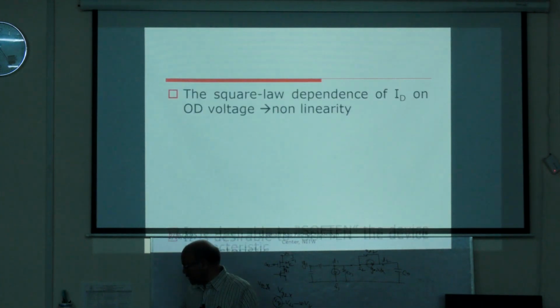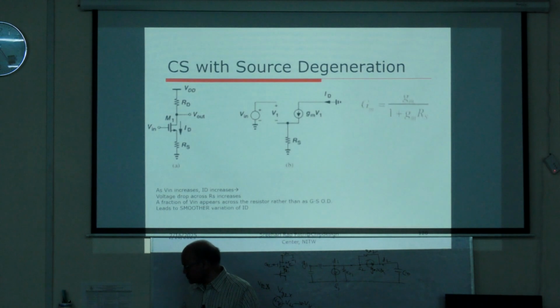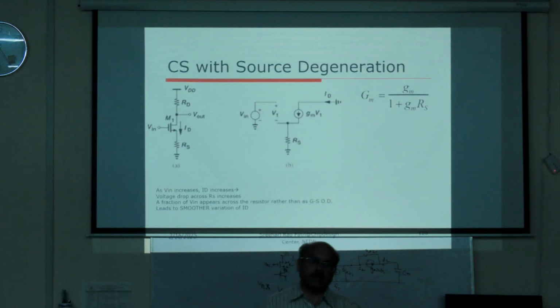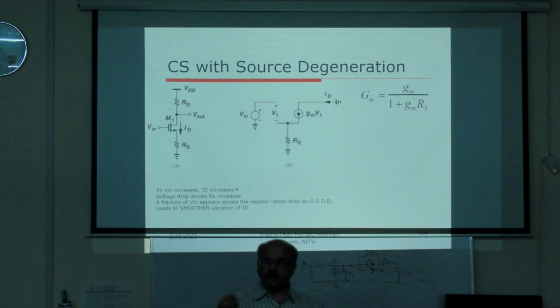So okay. Now quickly we would like to just know one more variation here, for the common source amplifier. When you try to give a voltage at the gate, you have seen that the current is a function of what? ID is equal to half mu Cox W by L (VGS minus VT) whole square. For small variation in the VGS, there is a square law relationship. Therefore, the current variation is varying by leaps and bounds. Sometimes we don't want that. We want to have a linear relationship between the applied voltage and the resulting current.